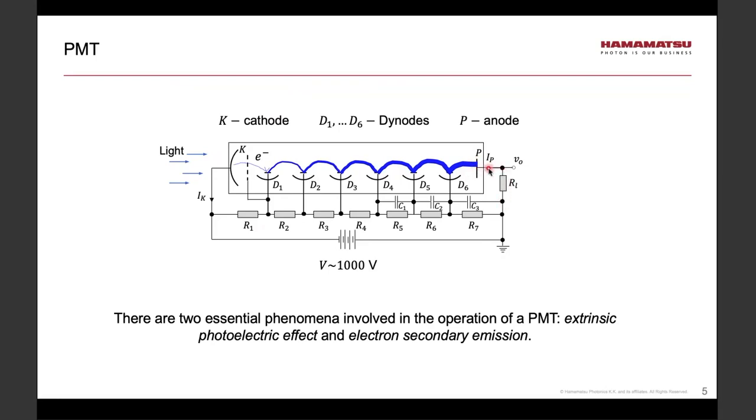In this depiction, we have a load resistor connected effectively to the ground. And so the conventional current due to these electrons flows into the anode as shown, and it has a value of IP. So in this description, we learned that a single electron or a single photon can result in a million or so electrons at the anode. And so PMT, we would say, has a gain, intrinsic gain. And that gain, as already stated, is very large, again, on the order of million or so.